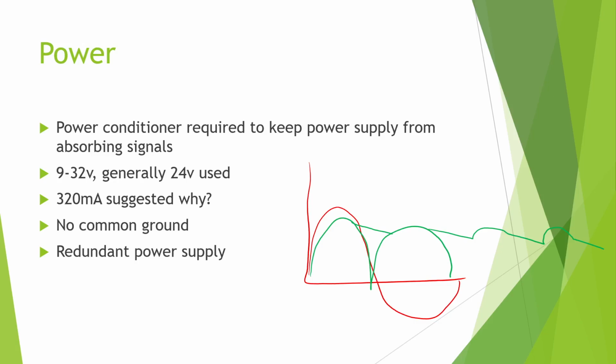All right. So no matter how big of a capacitor you put on an AC power supply, it is still always going to be a little wiggly. It is never going to be perfectly flat. Okay? And in the world of industrial applications for like PLCs and robotics and laptops and phones and things like that, that's fine. But if you have an instrument that requires a very, very, very steady power supply, your only option is batteries.